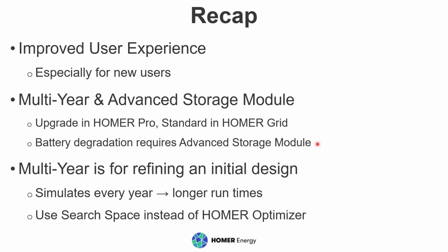But the other issue that's really important is, if you think about it, simulating every time step for a project life of 20 years or whatever is going to take 20 times as long for the computer to come back with an answer. So that's another reason why I use multi-year later in the process when I want those greater details. There's a third stage of project development where you're actually going to create as-built engineering drawings.